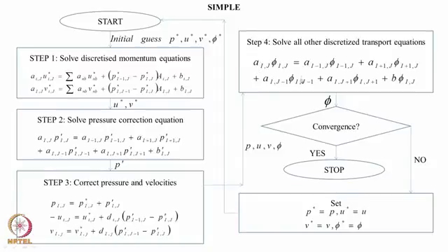We are still following the same procedure as we did for pressure or velocity variable. So, following the finite volume procedure, you get the generic form of the discretized equation. So, you get phi, then you set up a convergence criterion, you check whether it is within the convergence limit that you have defined. If so, you can stop the SIMPLE step or iteration and move to the next step.